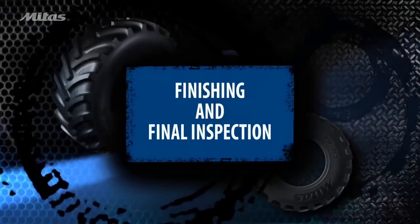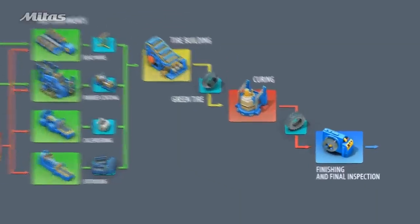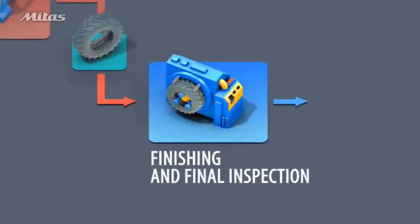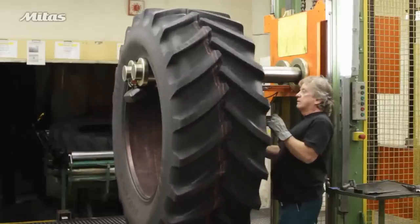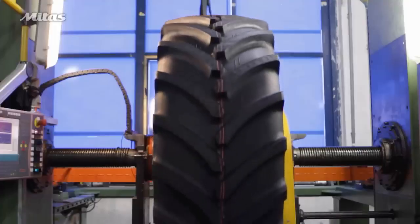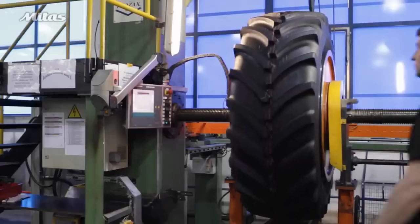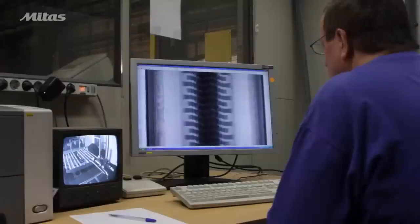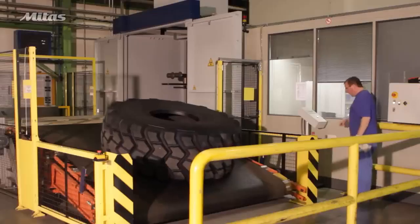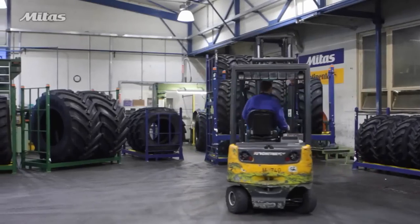Finishing and final inspection. Before the tire is dispatched from the plant, it is trimmed to order and inspected. Each tire is visually inspected for surface defects. Testing machines measure the compliance of central and lateral runout with the norms. All tires undergo a uniformity test. Tires containing steel cords are inspected by X-ray for internal defects. The final inspection is the last stage of the tire production. The tire is then stored and ready to be dispatched to customers.